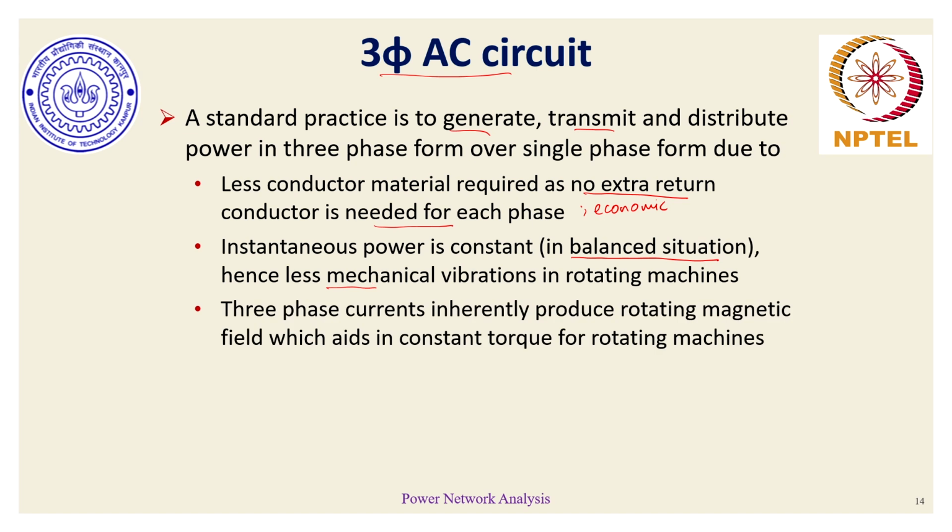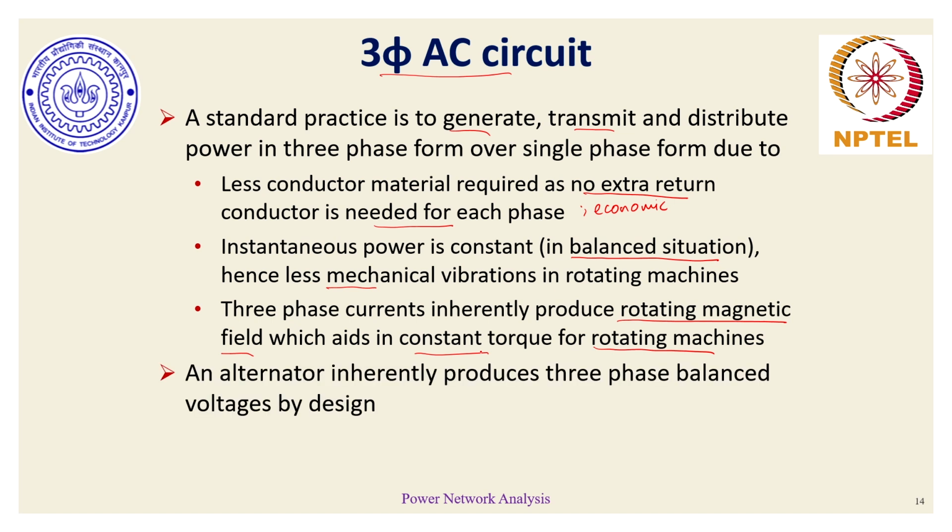Three-phase AC currents in rotating machines, specifically synchronous machines or induction machines, inherently produce a rotating magnetic field which forms the premise of operation of these machines, and it helps in maintaining a constant torque. And all these three different aspects of economics, less vibrations and inherent magnetic field, we'll discuss at length in the next few slides or lectures to come. And coincidentally, by design, a synchronous generator or alternator inherently produces three-phase voltages.